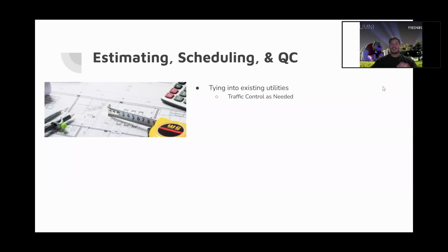And quality control, obviously you'll base yourself off the plan details, ensure everything is being installed per plan at proper elevation. Make sure you're getting enough clearance whenever there are systems in the same space, and ensure thrust blocks are of adequate size based on the specific pipe being used.